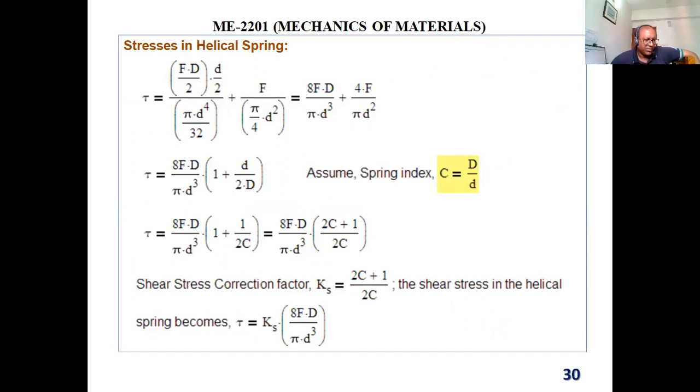Normally, if you know your applied force, how much deformation you want, and what type of material you want, and you have that data, then you can go to some company's website to get the spring, and see which one matches. Say you need a spring with spring constant K equal to